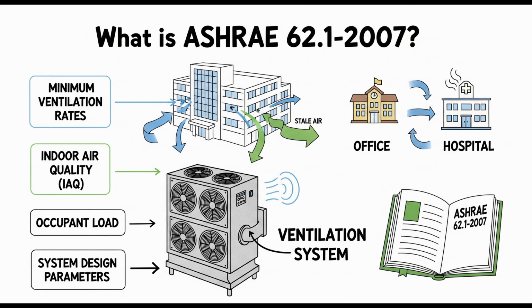So it's not just about cooling the air. You might need active dehumidification just to stop mold. Exactly. Under certain design conditions, like high outdoor humidity combined with low indoor heat load. And the building structure itself, the envelope, plays a part too. That's Section 5.15. How so?